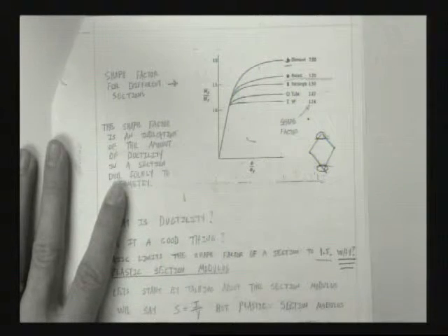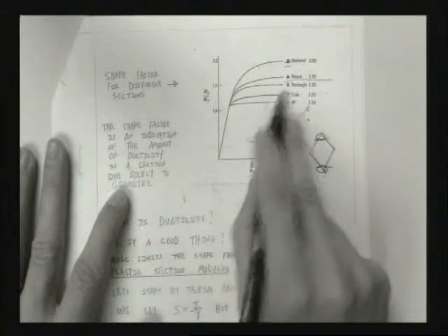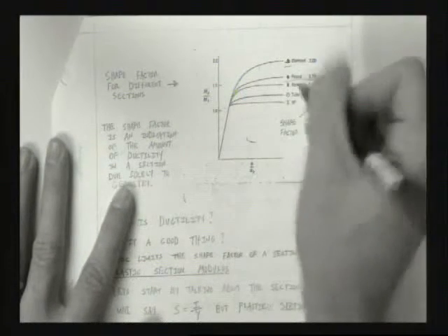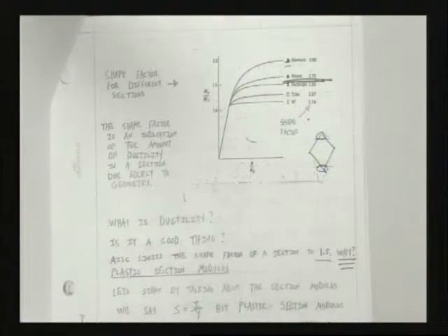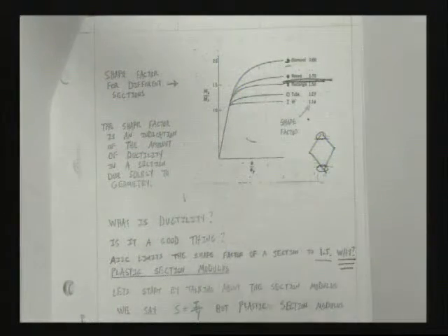Prime test question. We got round, we got rectangular, we got tube, and that's one reason why AISC cuts it right there, because it comes down to serviceability. We need to provide structures that are very serviceable. And we don't check for a lot of these serviceability limits. We do things like live load deflection limits. That'll be coming up.